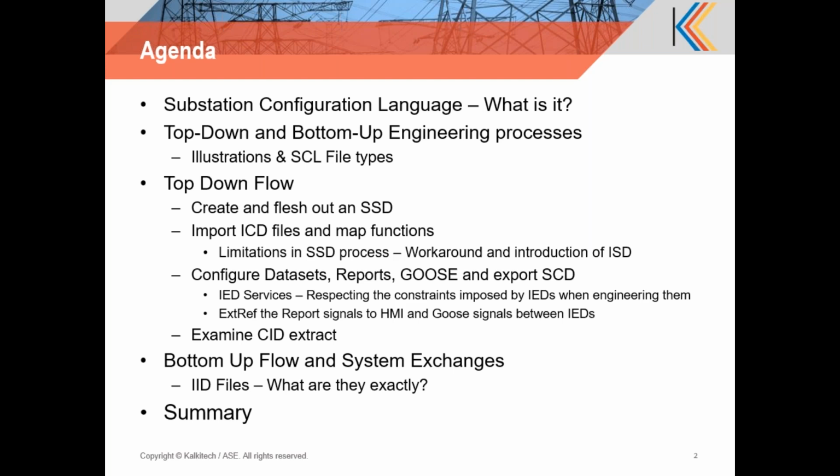We'll cover this with a few illustrations, and this would also be a good time to introduce the different SCL file types. As you may be aware, the list of types has been growing and continues to grow. For example, in the recent period, we now have the concept of an ISD file, an IED specification description. So we will probably spend some time to understand why that is coming out.